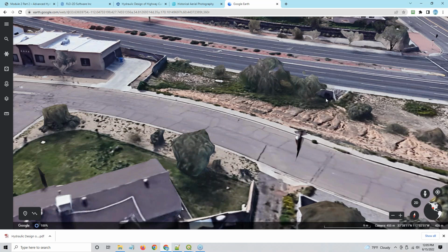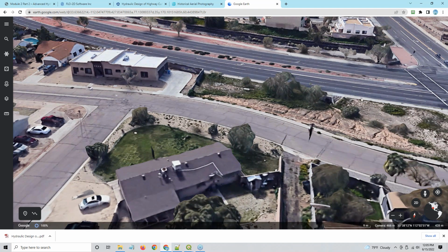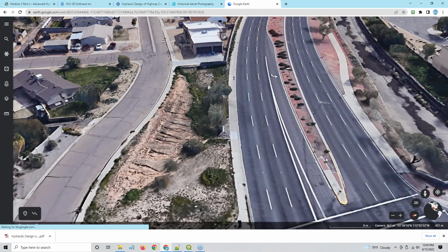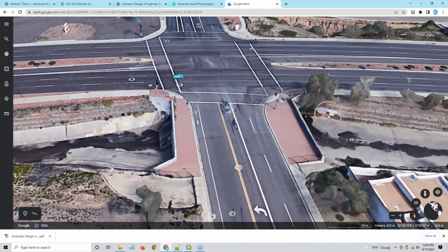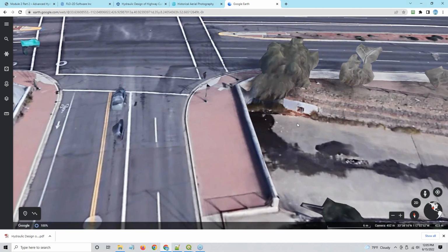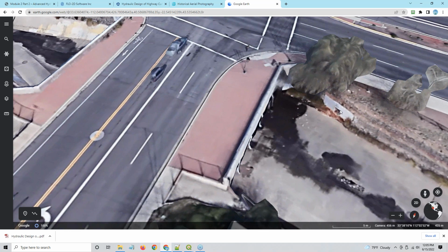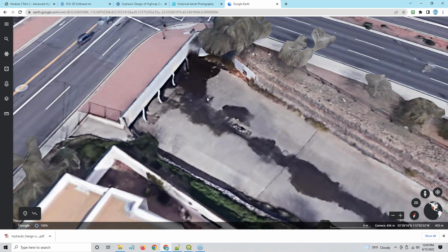So, 36-inch pipe, we know our invert elevation upstream because we picked it off of the elevation data. Now let's see what's happening down here and how this culvert pipe is connected. It looks like it's coming in right here. Okay, coming in right here, with a bit of a protective rack so nothing can get into this drainage channel. And the important thing about this structure is that it will be filling, there's no change in elevation right here.